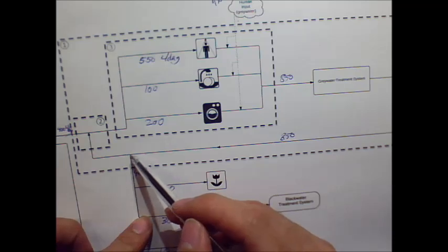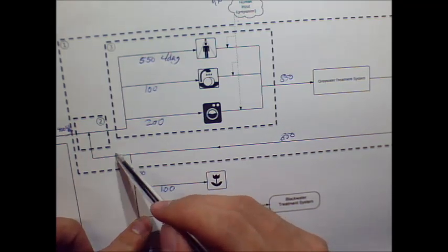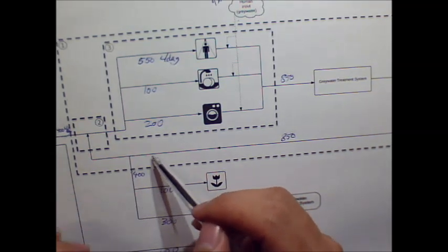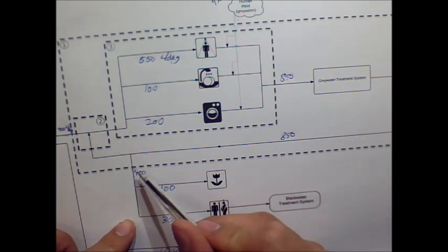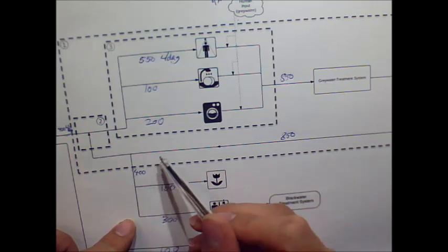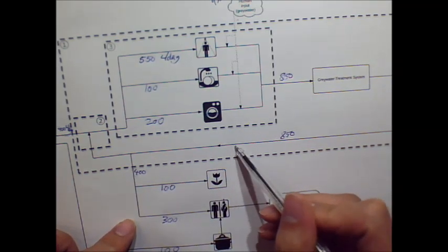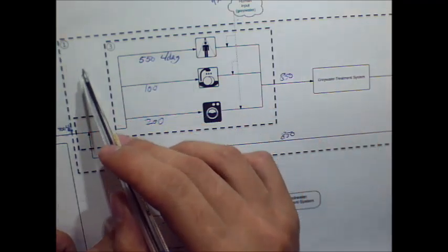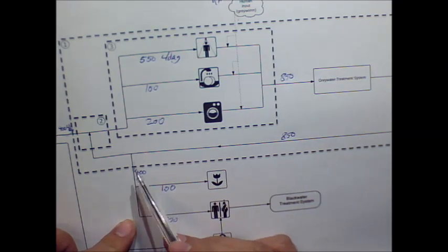Because at this point the stream splits into 2, this doesn't change the concentration at all. All it does is it changes the flow rate. You're essentially halving, or taking 40% of the stream off this way and putting the rest through that way. So if we find the concentration of the stream here, it's going to be the same as the concentration of the stream here, which is the grey water recycle loop, and that's what we're trying to solve. Therefore, we can just use the same system boundary as the first question, number 1, because it takes into account the stream that we're trying to find right here.